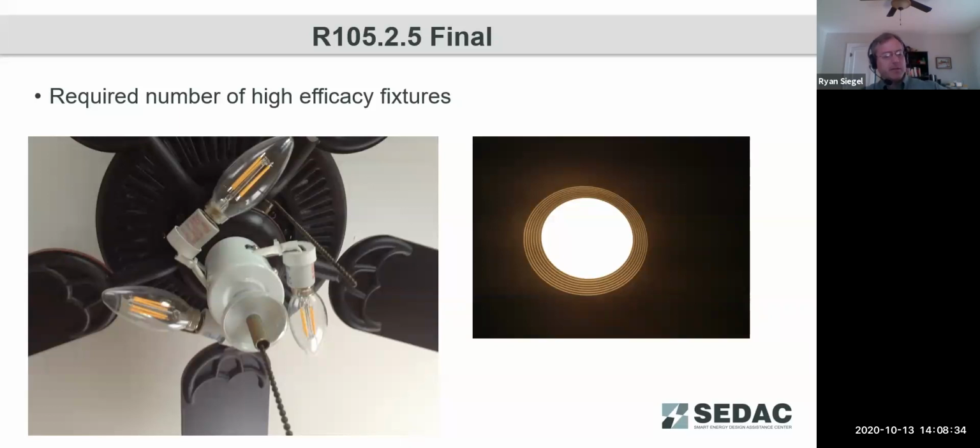Something else that may also be checked, if the duct sealing wasn't checked earlier, you might check that, including commonly missed is the longitudinal seam. So the one that runs along the whole ductwork, not just at the joints.